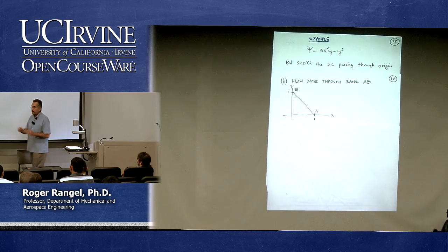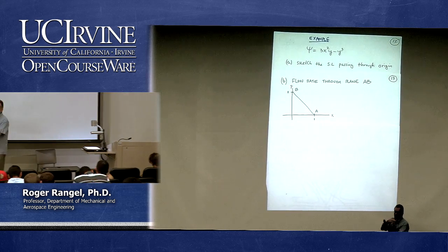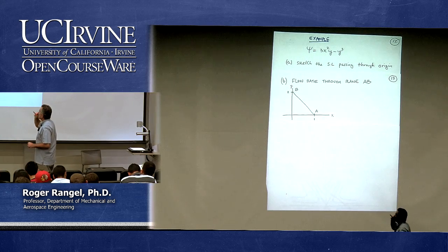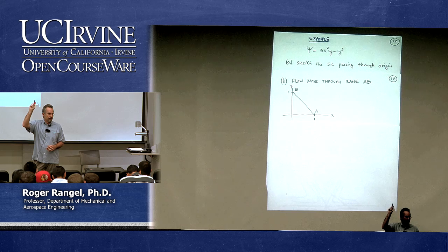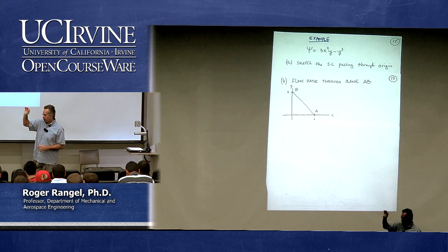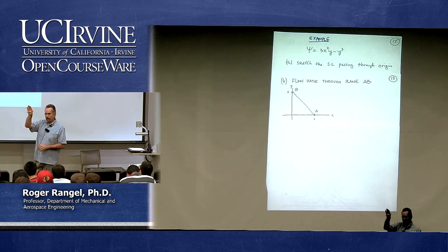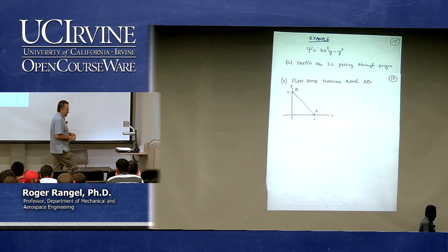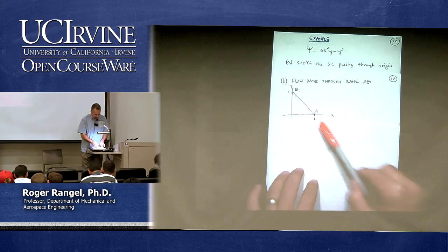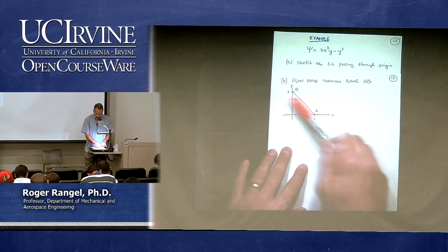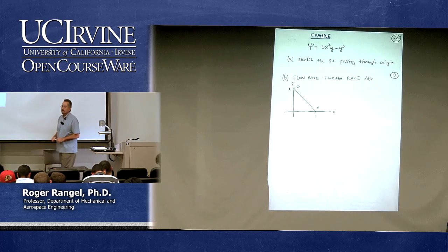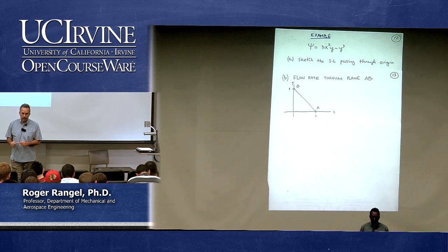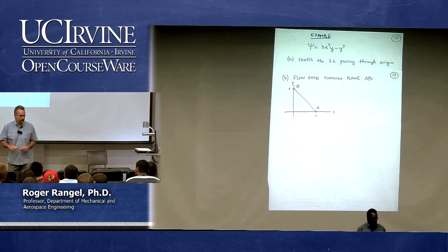So what we're doing is we're taking the coordinate system, x and y, and we're drawing a plane, which of course in the two-dimensional representation is just a line, but it represents a plane when you're thinking about the direction into the board, the width of the flow. So this is a plane that we call the plane AB. We want to know what is the flow rate that is crossing that plane. How much fluid, volume flow rate, is crossing that plane.